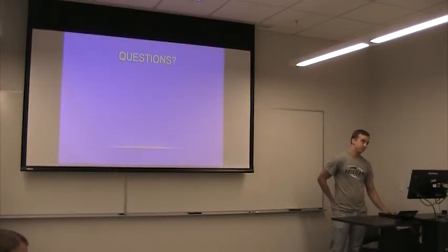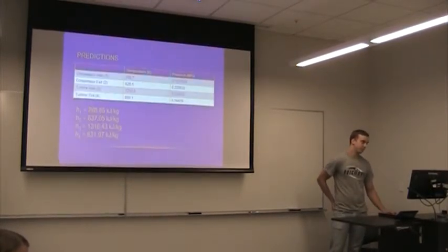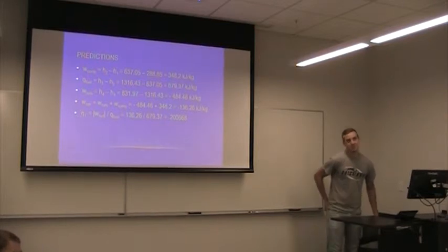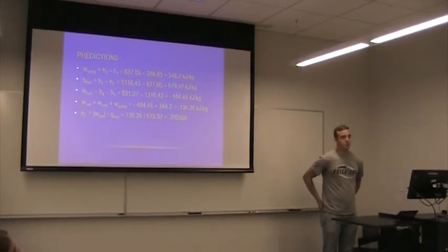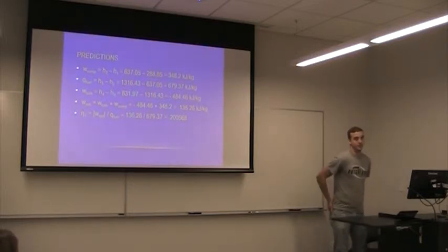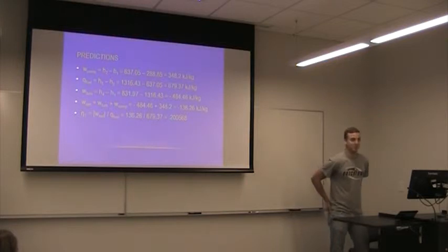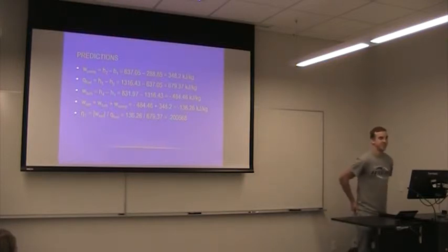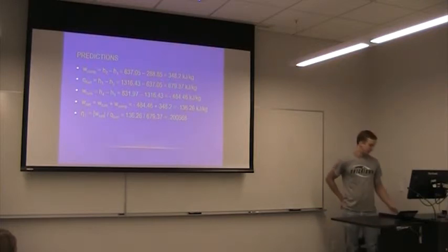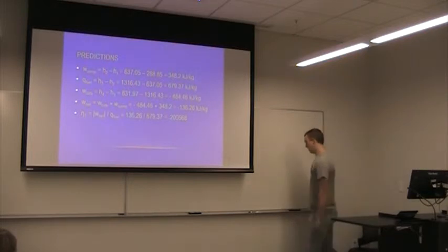When you get work from a system, is it positive or negative? Depends on your sign convention. So what is your sign convention? It says work being put out by the system was negative and work coming into the system was positive. Really? Is that what you guys did? That's what I did. I don't know what everybody else does. So what's your first law then? Write down the first law for me for the control mass, with your sign convention.